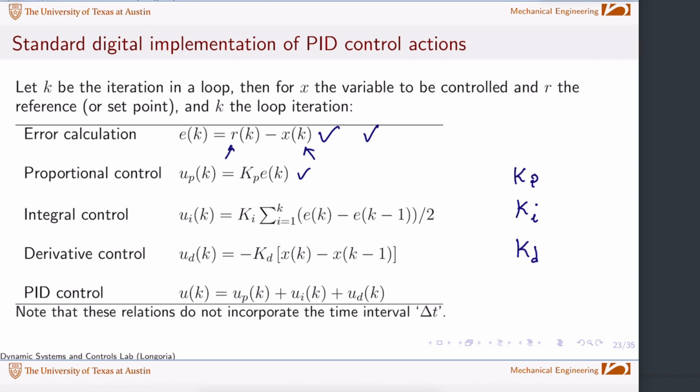And you can see that the algorithms are pretty standard. Actually, you've often thought of an integral. If you discretize that, you have the time step in there. But it's actually more common, if you look in some reference texts, that you don't even take into account the dt in there. Note that there's no delta t. You take the difference between the current time error and this step, and you keep the previous one, and you do an approximation, multiply it by the gain.